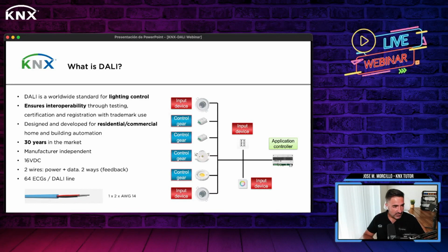Antoine is asking a question. KNX is also adapted to lighting control in the case of simple commutation and phase cut dimming. Correct, that's what I said. You don't need to go through external protocols like DALI. You can control loads directly from KNX. This webinar is about what happens if we want to integrate DALI, but you don't need to go to DALI. You have enough products in the market to control a full lighting system: 0 to 10, resistive loads, relays on off, many of them.